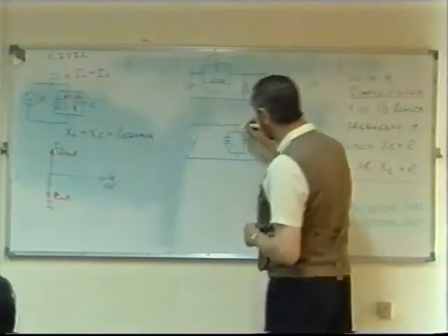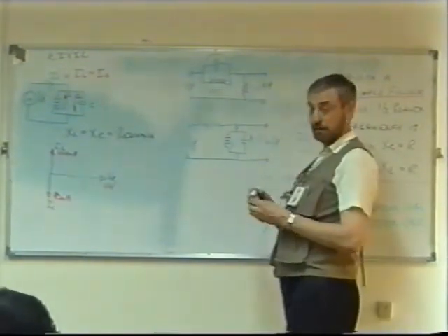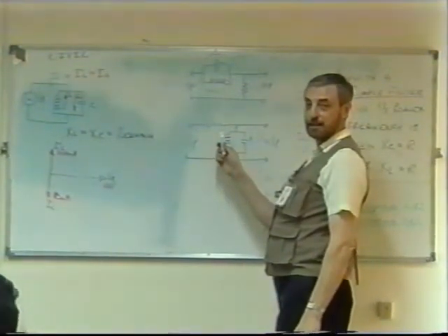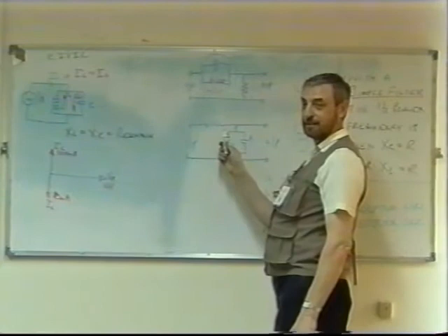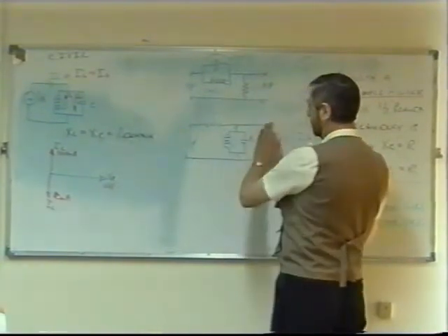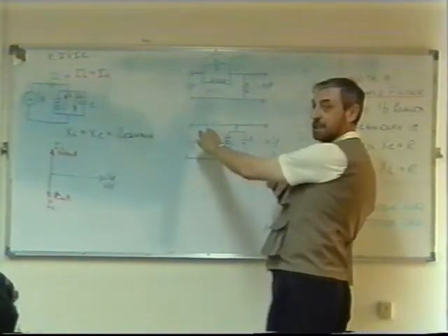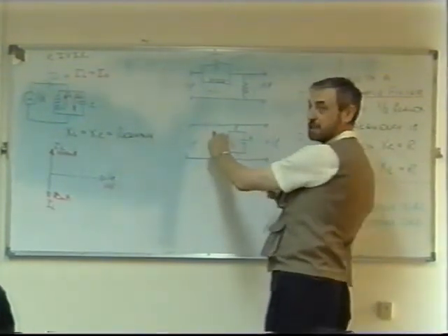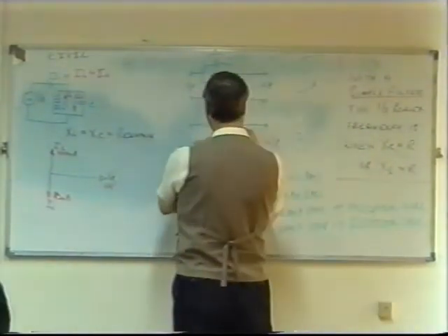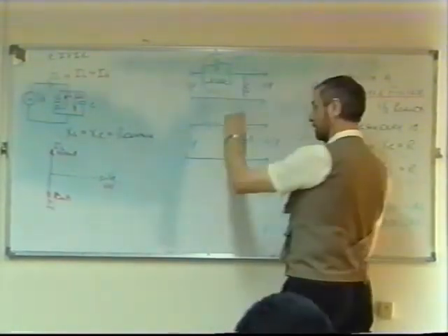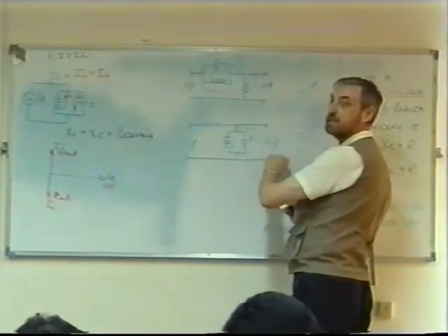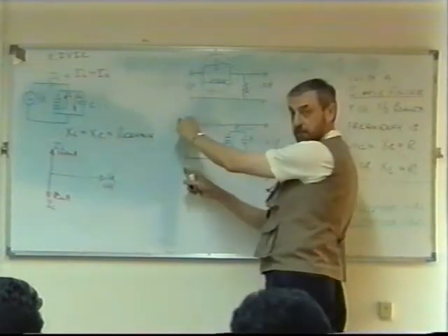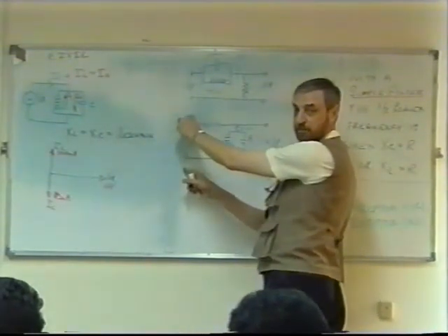So this current through here, if I total is zero, what's the voltage across this resistor? The voltage across the resistance? The output voltage is here. If this current is zero, and there's nothing connected here for the moment, there is zero voltage across the resistor. So the output voltage will equal the input voltage. Same as input voltage.